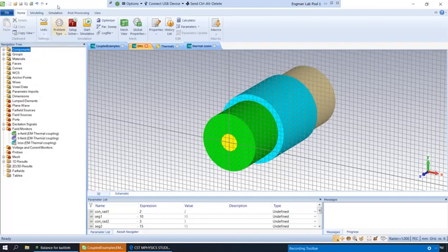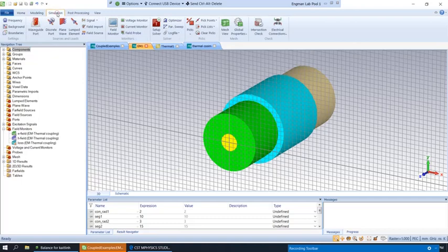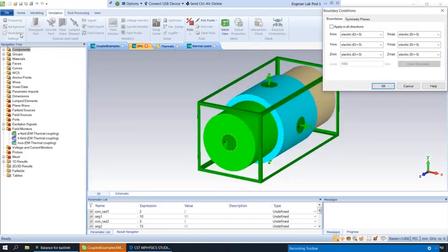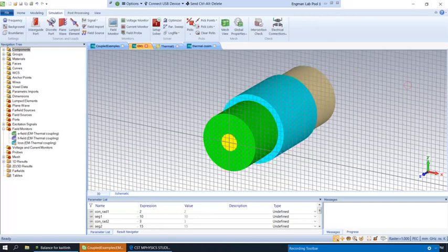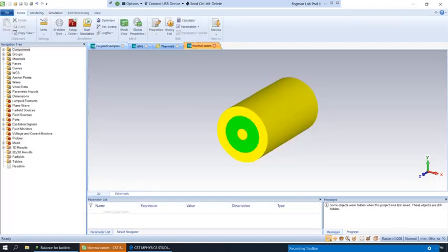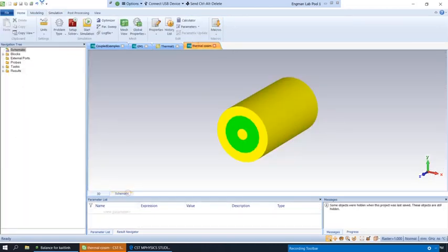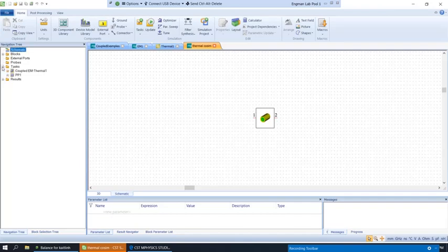The other things that we want to verify are the things that we would do for any simulation, and the things that we already did in that 2.4 gigahertz introduction simulation. And so that is, we want to check the boundary conditions. So right now, it is a conductive box on all of these sides. I'm going to go over to the CST example to see what boundary conditions they used in their simulation.